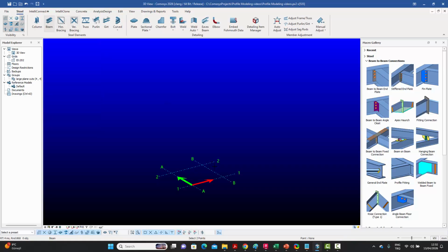So I'll use the beam command, and I start off from here. Because I want the top point to be at 3 by 3, and this total is 5, that would mean it would be 1 meter in the x and y directions from this point and 10 meters above this point. So I can click on enter over here, say at 1000, 1000, 10,000. And in this way, I can get my first section inside.